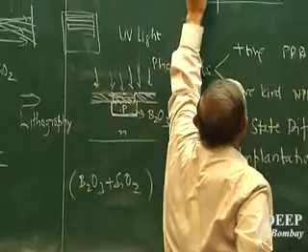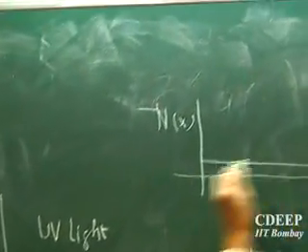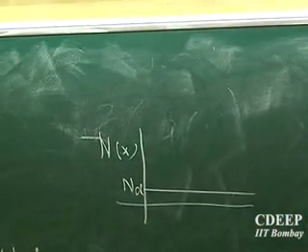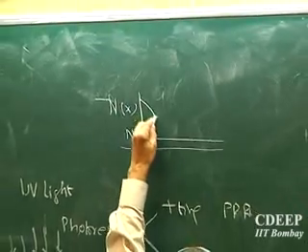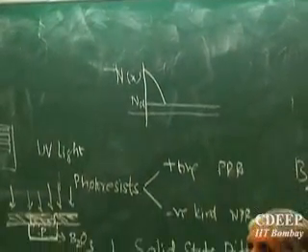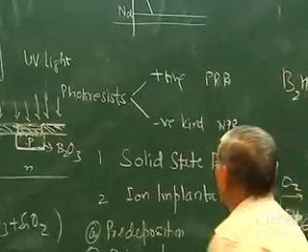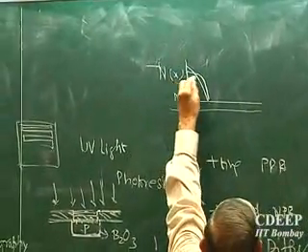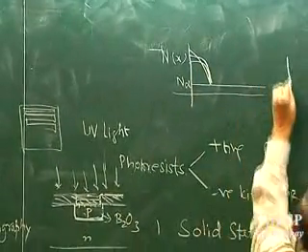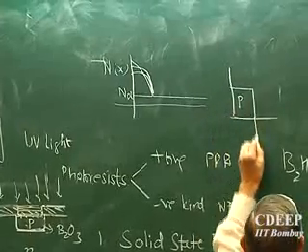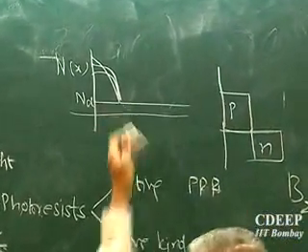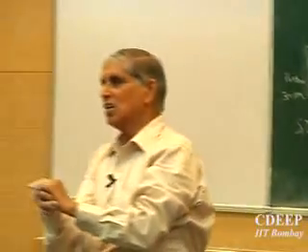If this is my concentration profile, actually this is minus, but let's say this is ND, which is the substrate concentration. From the diffusion side, I will introduce impurities which give a profile called Gaussian. Which profile? Gaussian. How would I make the Gaussian? Like this. This will look like one side P, one side N. This is negative because of opposite polarity. So this, in which one side is P and at the junction the other side becomes N, is called an abrupt junction, P to N. In reality, there is no abrupt junction. There is a profile there.